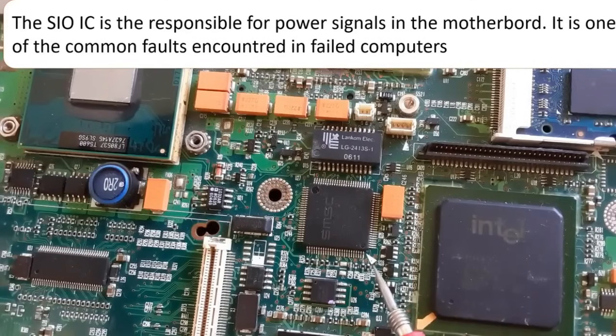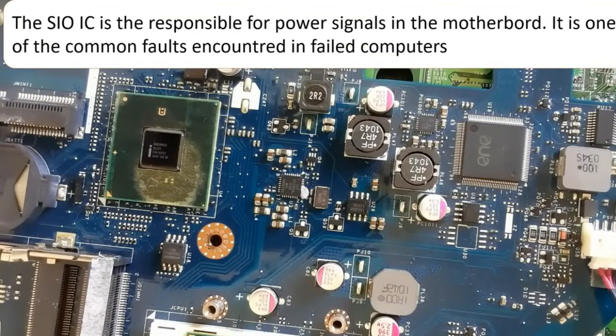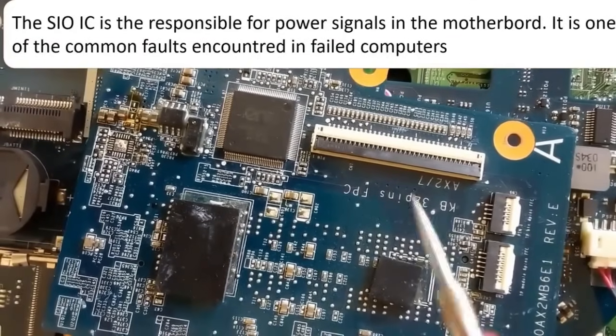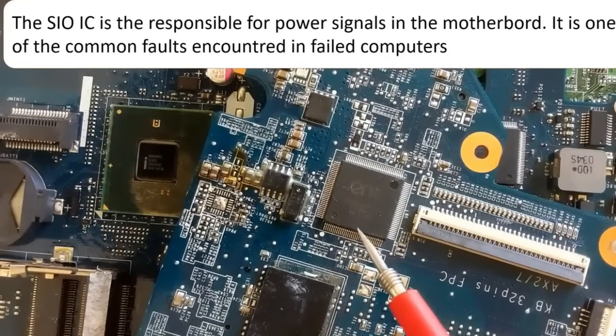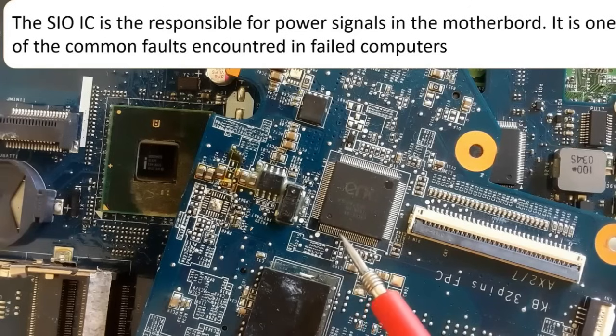So this is the Super I/O. This mark means we have pin number 1, and this is the direction of reading. Always read counterclockwise. The Super I/O is near the ICH and the BIOS. Here on the motherboard we have another Super I/O. This dot means pin number 1, and this is the direction of reading.